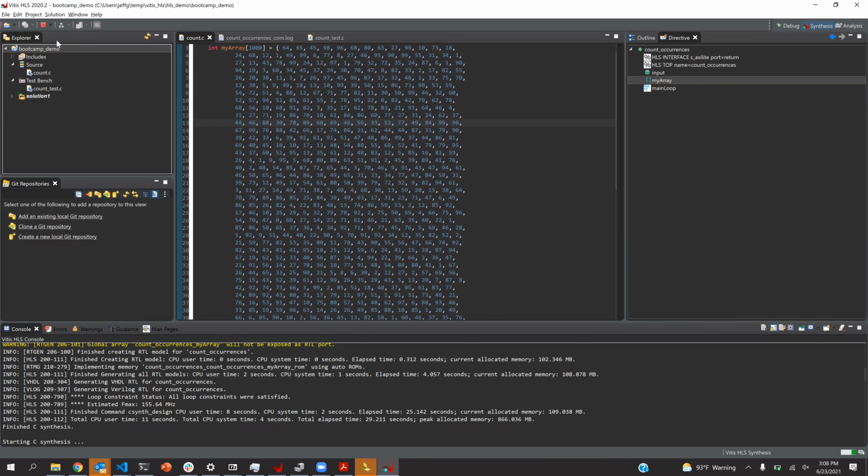When it's done, in this next drop down, there's an export RTL. It'll take this and package it up and create an IP that you can drop into your block design in Vivado and wire it up to the bus just like we wired up the GPIO on Monday. So again, you can build a whole hardware system without writing a line of Verilog.